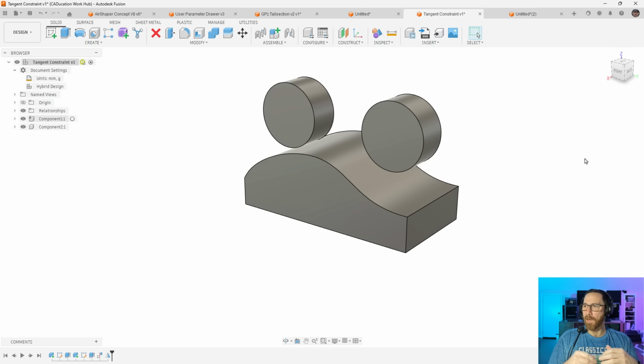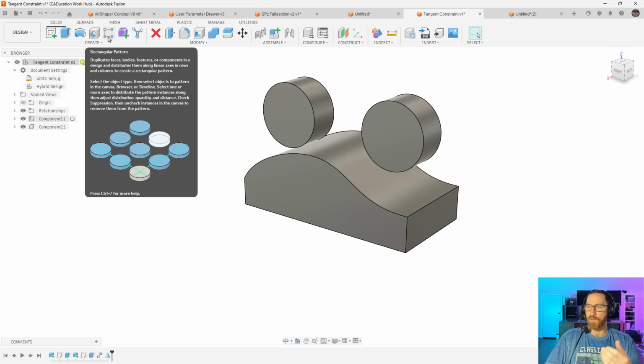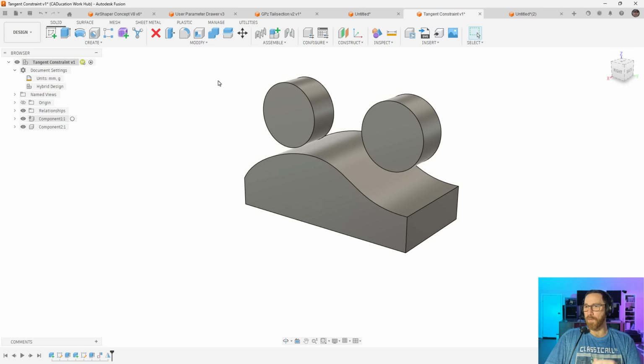More so for me than setting the default to identical, having it remember what my choices are is important. This comes across on a lot of different features, and I wish that it was pervasive throughout all the things that we do in a Fusion session. If you are constantly doing things like adding a joint or copying or doing things like that, it helps if it remembers the last setting, because a lot of times it is the same thing. So those are some changes that have happened. Again, kind of unifying the location of some of these options with the patterns, and it applies to all the patterns. If you're doing something like a feature pattern, it'll give you the identical by default, but it will remember what you're doing as well.